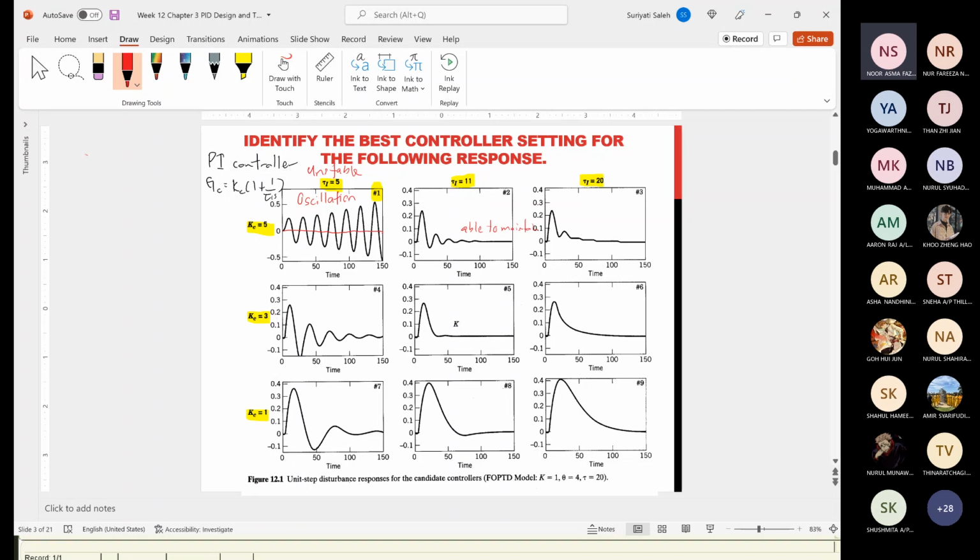However, in this case, you have oscillation in the beginning of the response, like a second order underdamped response. You have the overshoot, and the process also has an oscillating pattern before it is maintained. So two main findings can be interpreted from this graph. First, by increasing the tau I value from 5 to 11, you are able to eliminate oscillation on the whole.